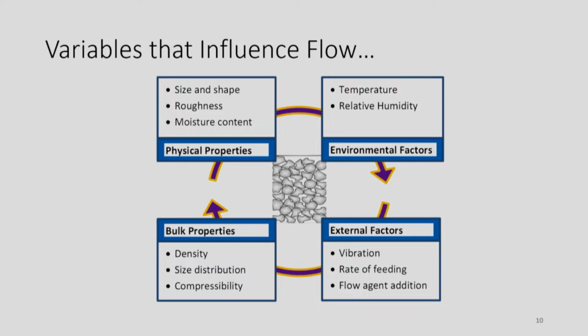So again, for liquid, we use the simple equation P equals rho GH, right? Density times gravity times height, right? So with increase in height, the pressure will also go up, directly proportional to height, right? But for grains and material, the pressure doesn't go up directly proportional with the height. Okay, I'll give a clue. Just above 1 or 2 meters, there will not be any effect from the height. I think it's close to 2 meters, and again it depends on the powders too. Above that height, there will not be any effect from the height.